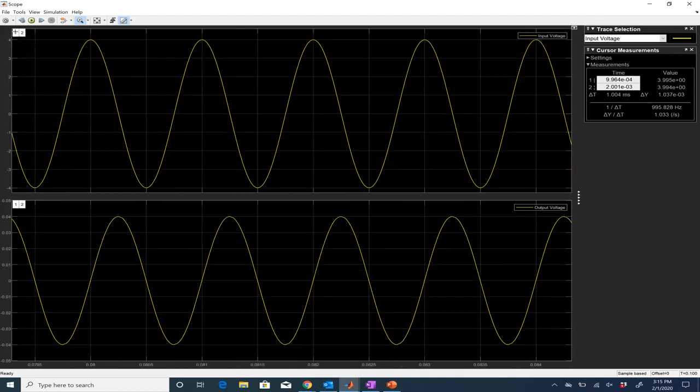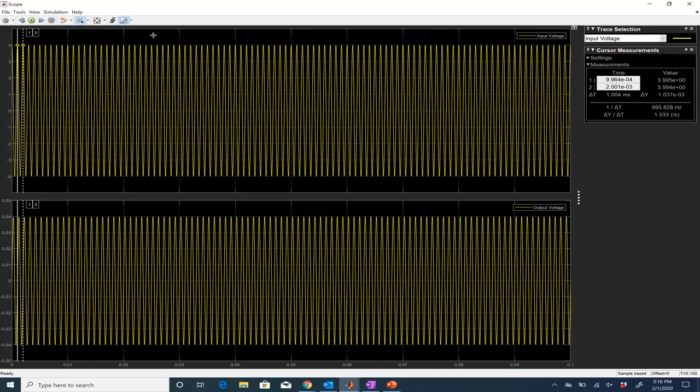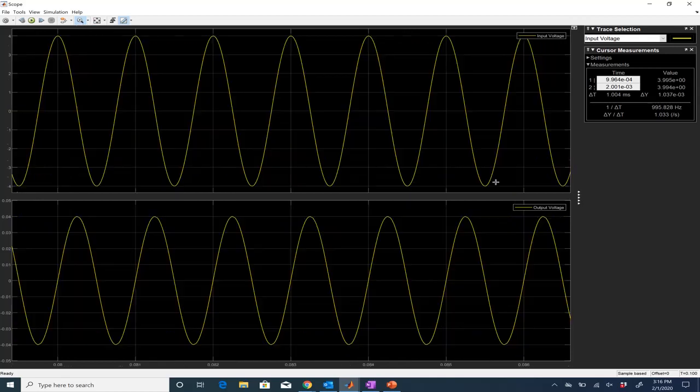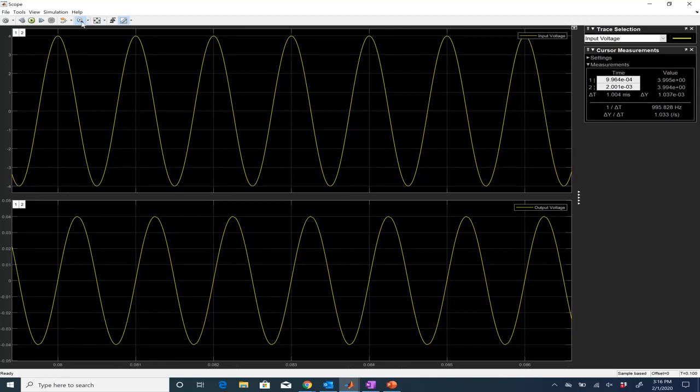And what I want to do is measure the time delay or the phase delay between those two waveforms. So in this case, oops, go back to my magnifying glass. Okay. Now I want to use the cursors again, so I turn off the magnifying glass. So I basically left clicked on it. And then I'm going to left click on number 2 and drag him over here, and I'm going to bring him into the screen. I'm going to do the same with number 1.